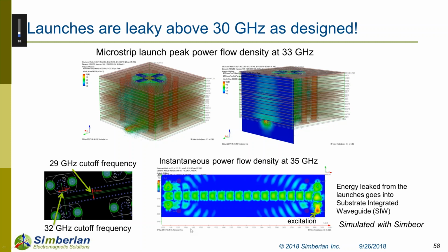Localization in general, every time. Also, I put some structures, for example, single-ended vias, where you don't have any return vias nearby. Those things resonate, and there's a lot of ringing going on. So if you want to build predictable interconnects, it's very important to only build structures that you can accurately simulate. The boundary conditions you put in your 3D field solver have to really mimic what happens on the board.